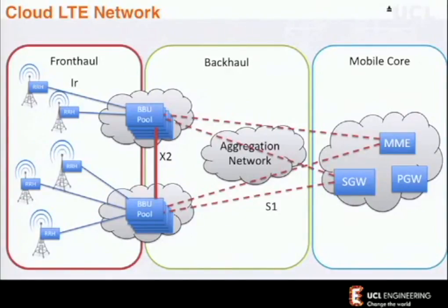Obviously, this is simplified if now all these base stations are in one single point. We've now not got multiple links. And if you start looking at the LTE networks, you'll see a mesh of these X2 channels between all the base stations. So having a dedicated mesh between base stations is both a costly and slightly messy thing to have to do. The S1 interfaces back into the network can also be simplified, but that's not so much of a huge deal. But how each of these, what would have been separately located base stations, communicate can offer real advantages to what we can do.